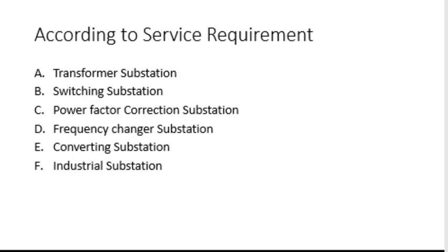We can say that the power switching of different power lines will be done, or you can say the transposition can be done at these substations, because as we have already studied in the transposition part in transmission parameters, transposition is always done in a substation only. It will not be in the middle of the particular transmission line when we are laying it down.